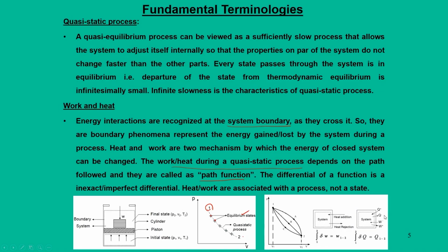When you take out heat, we call this negative, and in the same terminology, when work is done by the system, we say it is positive, and when work is done on the system, it is negative. So, all these notations have to be followed side by side. Heat addition means positive, and work done by the system means positive. With these notations, all other consequences can be framed.